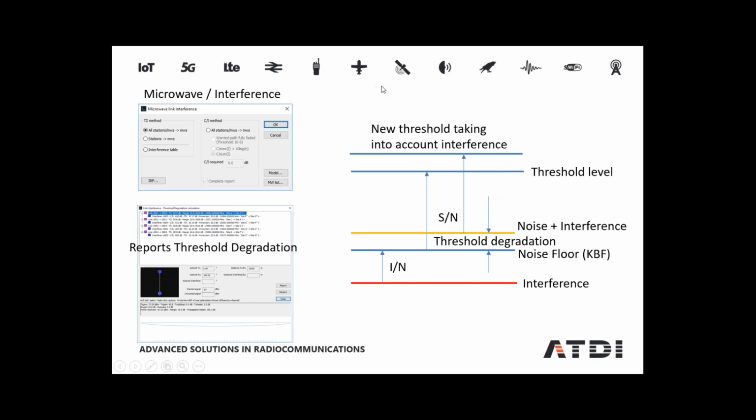So you can see here, if we imagine a signal up near the top of the picture being the wanted signal, because the threshold has degraded, the fade margin has decreased, therefore the availability has decreased. So if the system had been designed for 99.99% availability and the calculation was 99.9999999, close to the threshold level, that 1 dB may have pushed it over the top. Now, if it just pushes over the top, fine, but if it gets any worse, you need to start taking it into account.